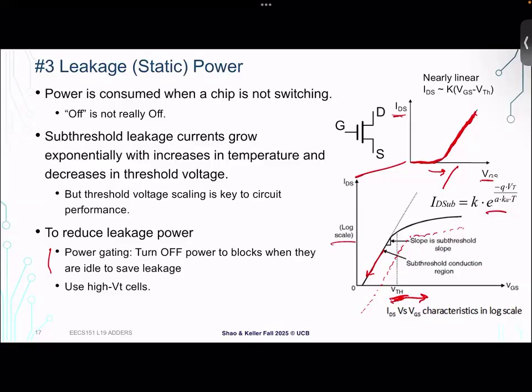In a typical CMOS process, you'll have multiple families of transistors to choose from and gates designed from those transistors. So for any given inverter, in addition to its sizing, you can decide whether to use a high VT inverter or a regular VT inverter or a low VT inverter. Typically, there's at least 3 or 4 different families of these threshold voltages, which are set based on different amounts of doping in the silicon process.